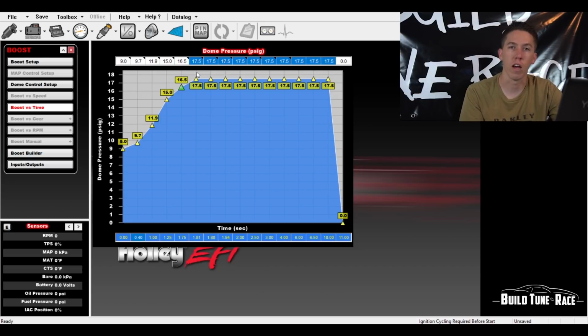If not, you could have 5 pounds on the spring, add 1 pound, the car makes 6, add 2 makes 7, add 3, and so on. That's kind of where you can see that it's efficient, everything's good, and then when you start getting a higher boost, you might have to add more to make that next pound of boost. Every car is different when it's set up like this. It's all in how your hot side, your cold side's designed, how everything's set up and works.